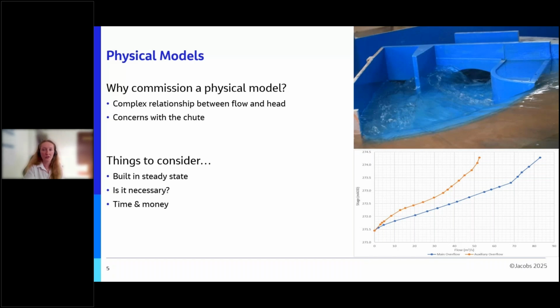Flood Modeler, on the other hand, is much more adaptable. You can easily change flow distributions or gate settings, but this is not so easy to do with a physical model, making it difficult to integrate into the computational model. Instead, you could use an FM weir unit and treat the physical model data more like a calibration tool. Then, when you do change your model settings, you may be able to better represent different situations.